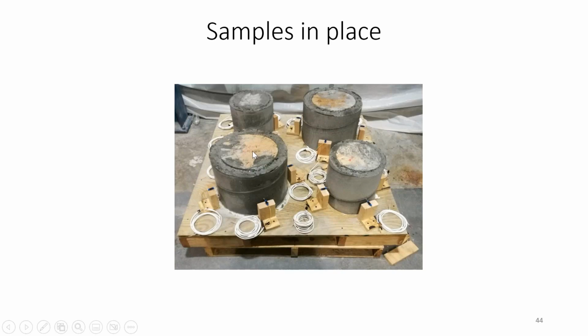For example, if the timber pile is dry and you wrap it with the UHPC and then it becomes wet, it's going to increase in dimension and create hoop tensile stress and cause cracking. The way we got around that issue was that before we cast the UHPC, we placed a very thin layer of foam to separate the timber pile from the UHPC, and that solved the problem.